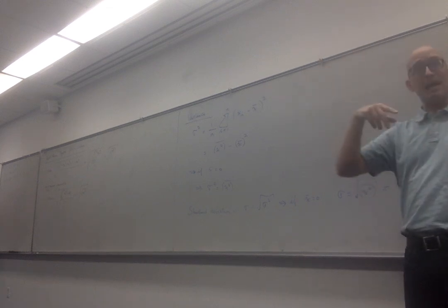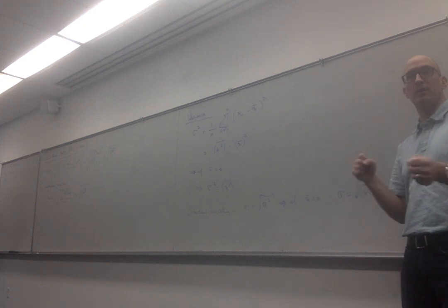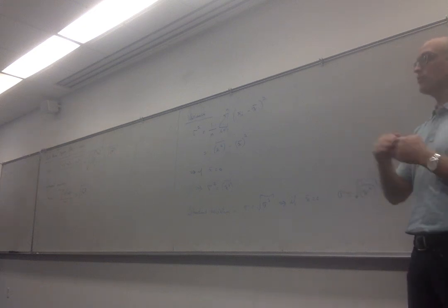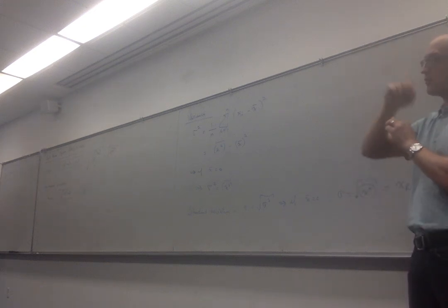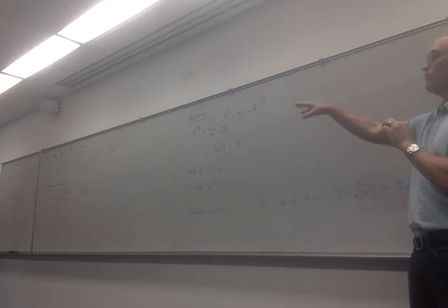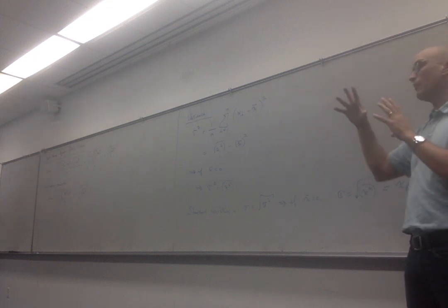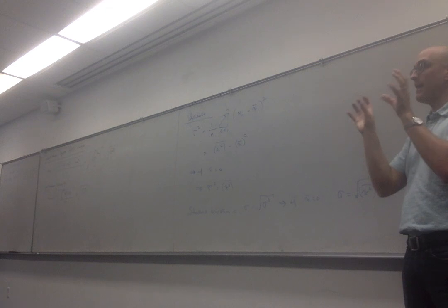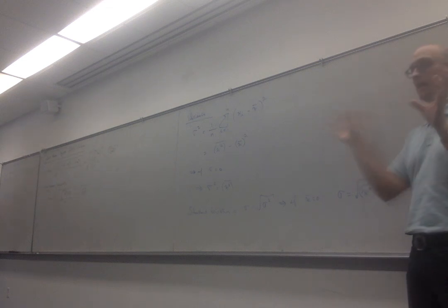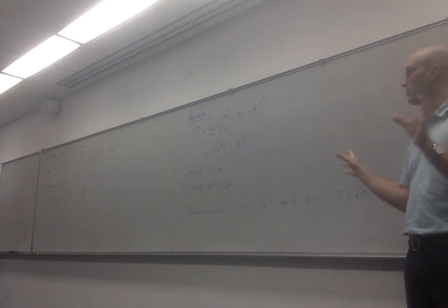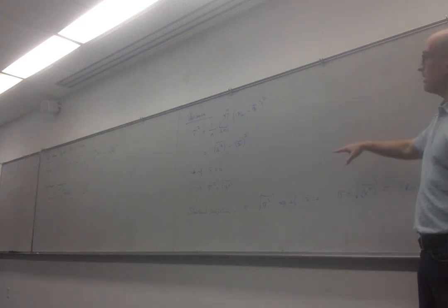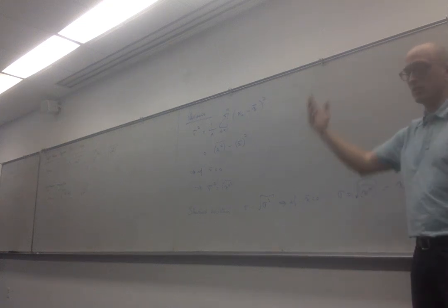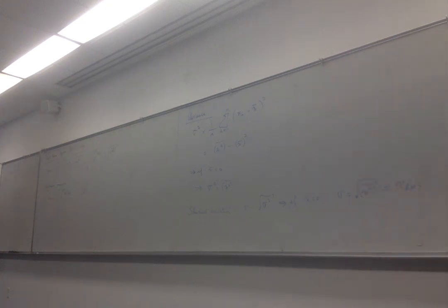You typically remove the impacts, like a pothole, because these are not vibration. Those events with very high acceleration are typically removed. Then the signal is broken down using a Fourier analysis into main components, simple sine vibrations, and you get the power spectrum density that's created.